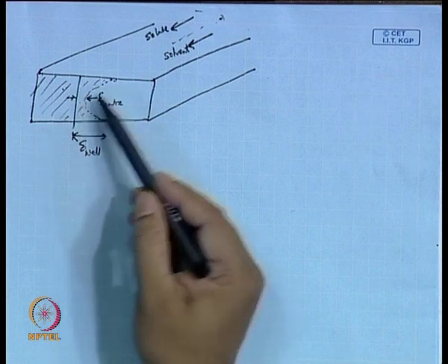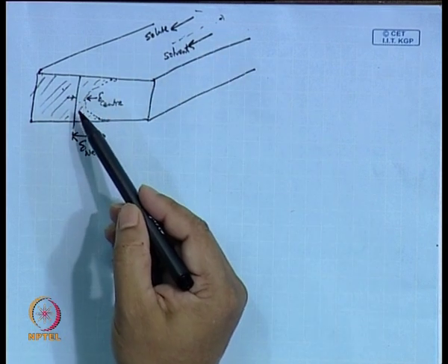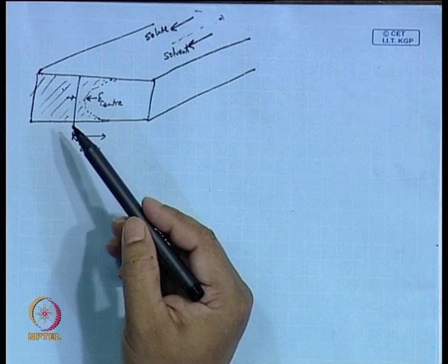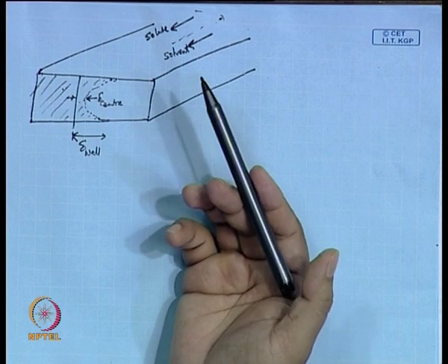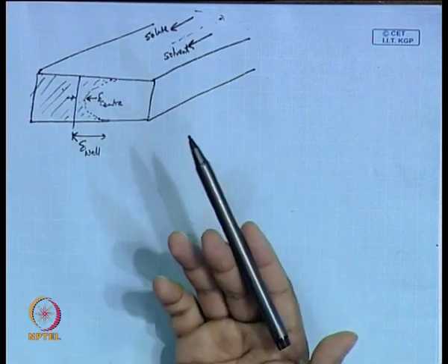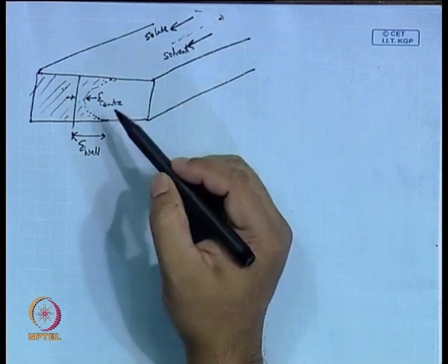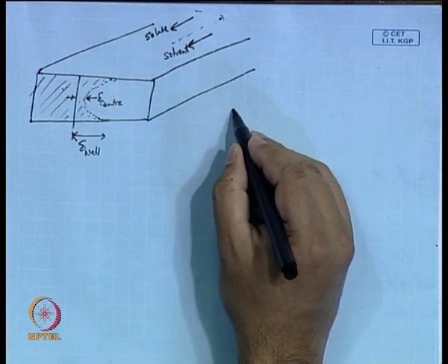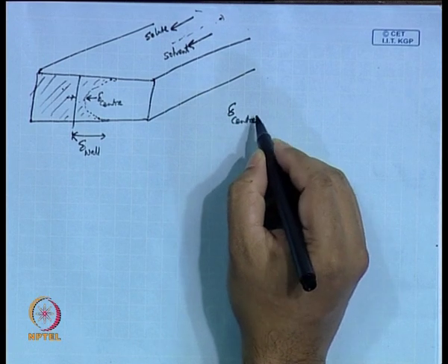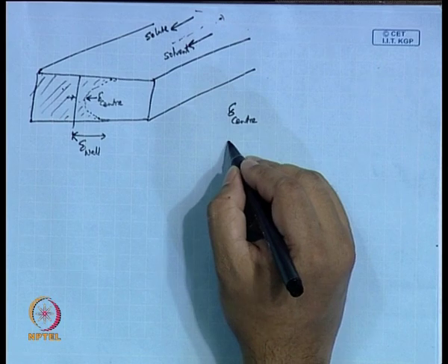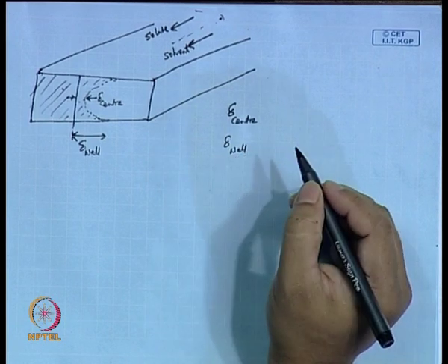The stream that is coming at this place probably had the least residence time inside the channel. So that is why you cannot expect the solute to penetrate far into the layer at that place. So this is how it is. Now, what researchers have done is they have numerically found out this delta center, and this delta wall.